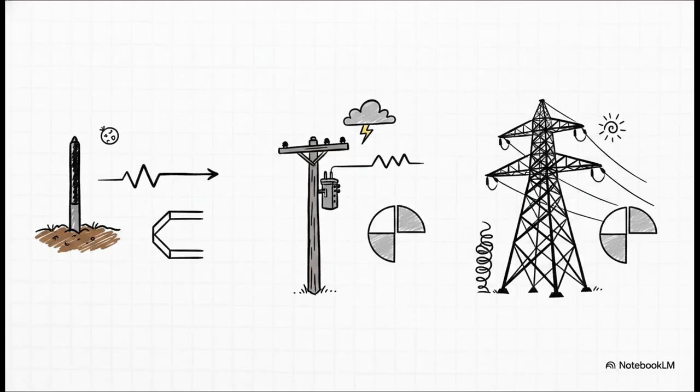So, the absolutely crucial takeaway here is that the choice of this relay characteristic angle is not random. Not at all. It is directly dictated by the physical earthing characteristics of the power system you're trying to protect. If you're on a resistance earth system, the fault current is more resistive, so you use a 0-degree RCA.